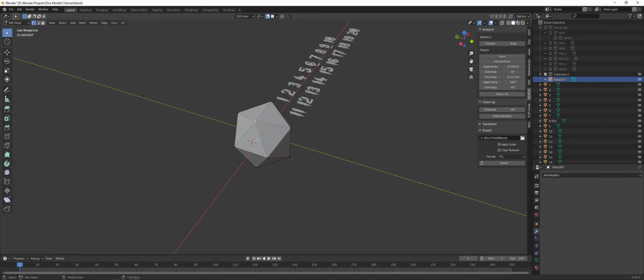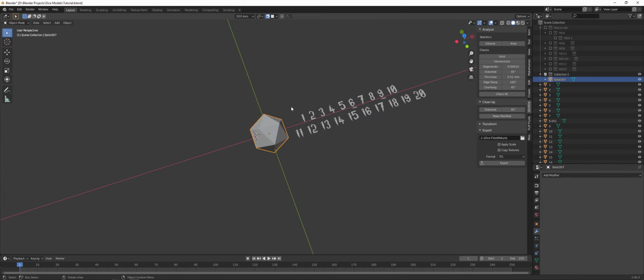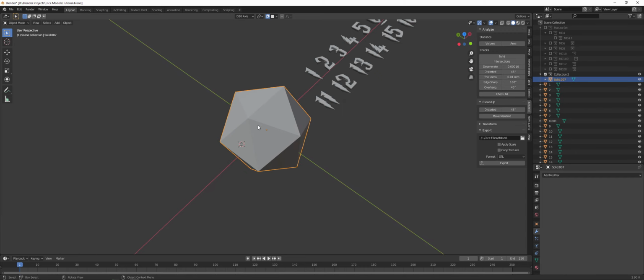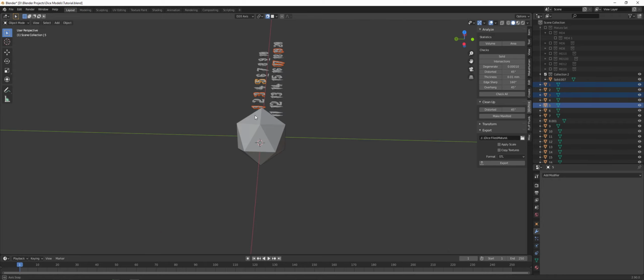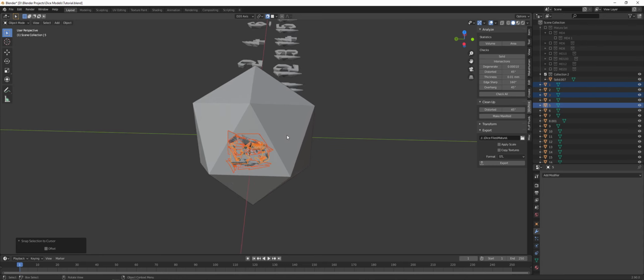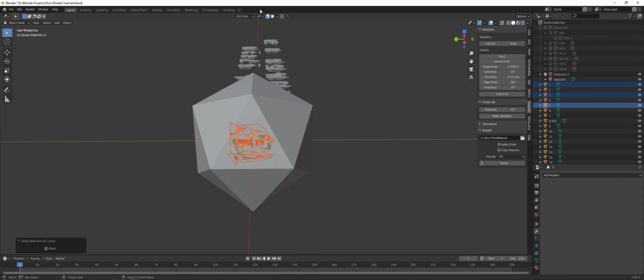You select the face that you want, and it has to be one of the faces that's aligned with one of the points you're gonna choose as your top and bottom. Then go 1, 19, 17, 3, and 5. Place them there, just like you've done with all the other ones. Make sure you're on local coordinates. Rotate C 90, no, minus 90.